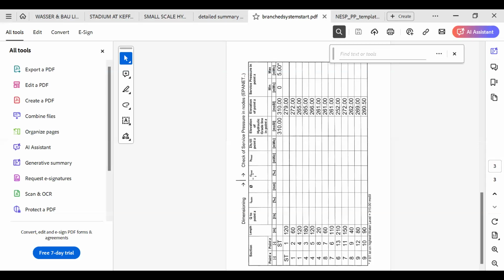This is elevation real, slope real. This is slope, which is per 1,000. This sign means diameter in mm. This one means real, because if you remember last week when we were using the nomogram, you might not get the exact slope you need. You might not get the exact pipe you need. You use the closest pipe. And when you get this closest pipe, you can go back and recalculate the actual slope. We will still come to that. Then you can go back and calculate the actual losses and the velocity. We'll still come to that.